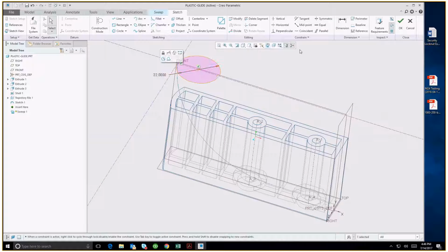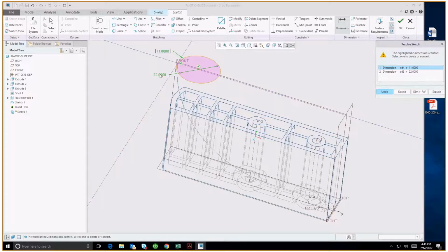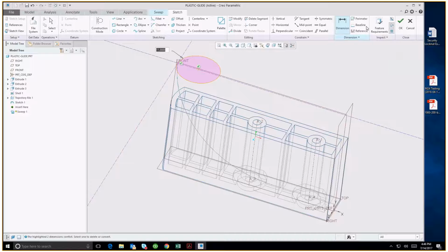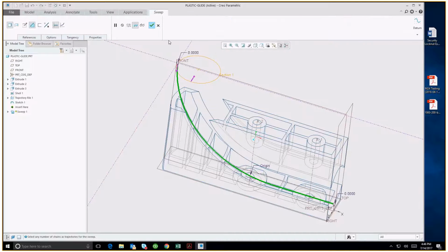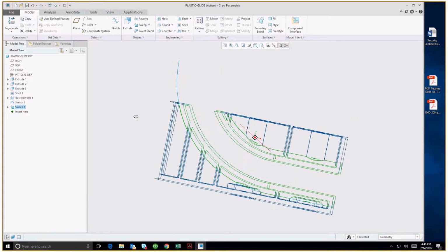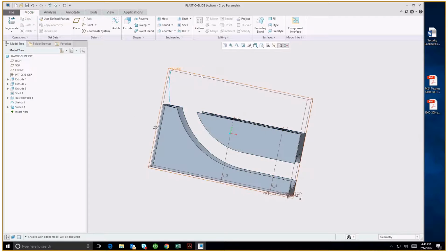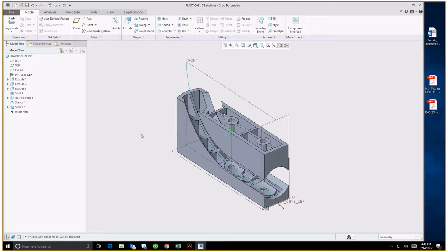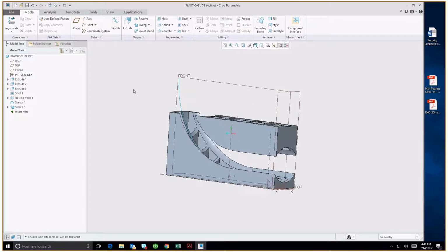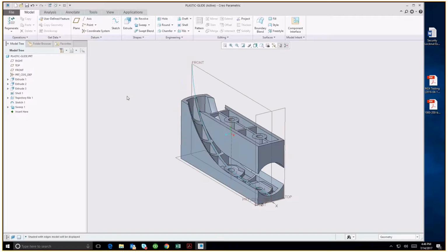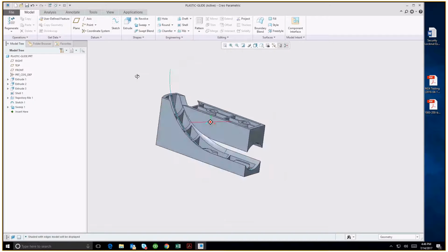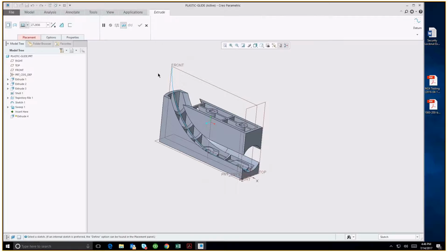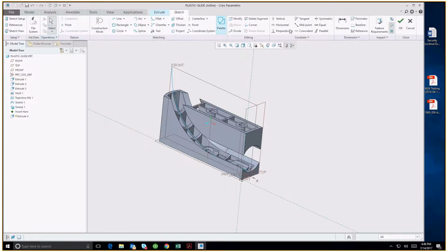22. And that's actually a radius dimension. Get rid of that one. And we cut that away. Okay, so looking good so far. Got some extra material we got to get rid of. So we'll get rid of that along with an edge there. So I'll sketch this.